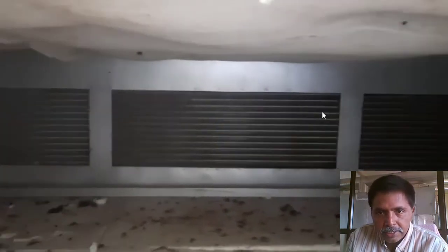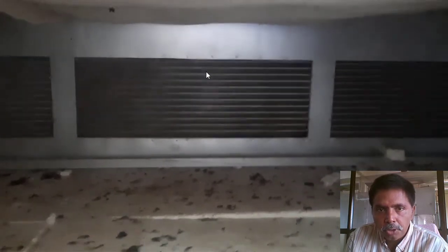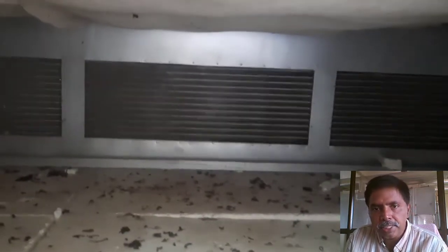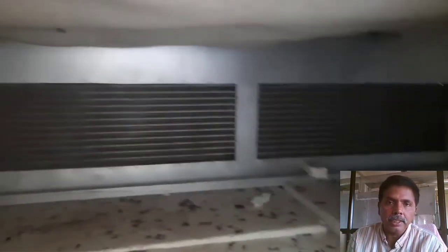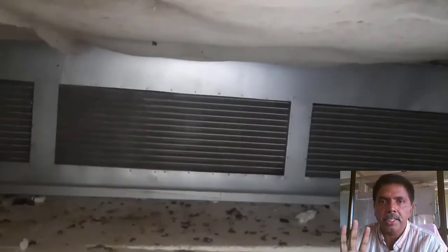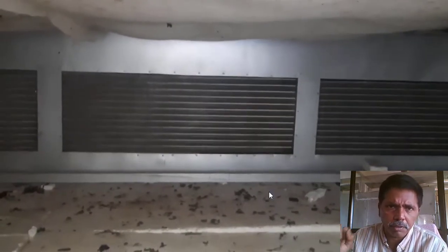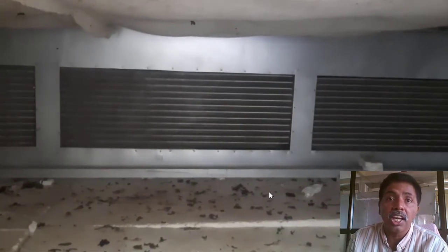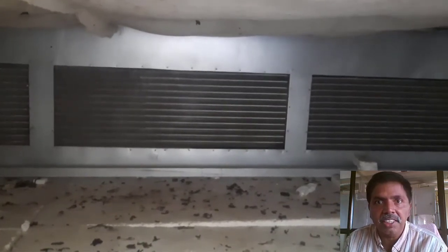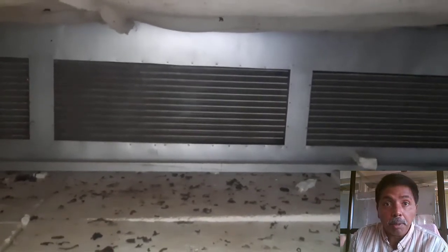This is the heat exchanger. Through the heat exchanger pipes, heat transfer fluid is moving. Through the fins, the compressed air is entering inside the dryer. We generate 20 to 30 degrees delta T more than ambient inside the dryer cabin. Based on the product, it is not fixed. Suppose fish drying, 10 to 15 is more than sufficient. Onion, 30 to 40 degrees is sufficient. So it varies from product to product.